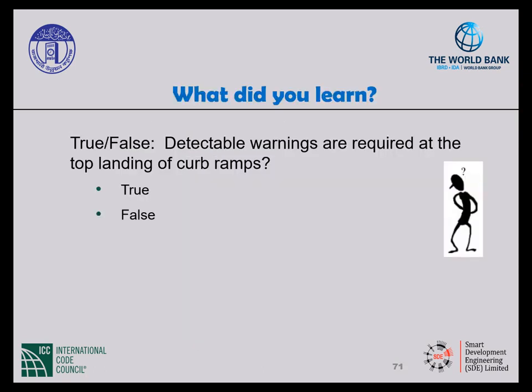What did you learn? True or false? Detectable warnings are required at the top landing of curb ramps. And the answer is false.